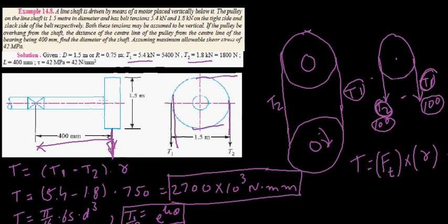So I hope you're getting it. If, for example, I want to know the bending moment at this section, then I'll take whatever the force is multiplied by this distance, and I'll get the bending moment at that distance. So you can feel that the maximum bending moment would be this force times this distance, because this is the maximum distance achievable.